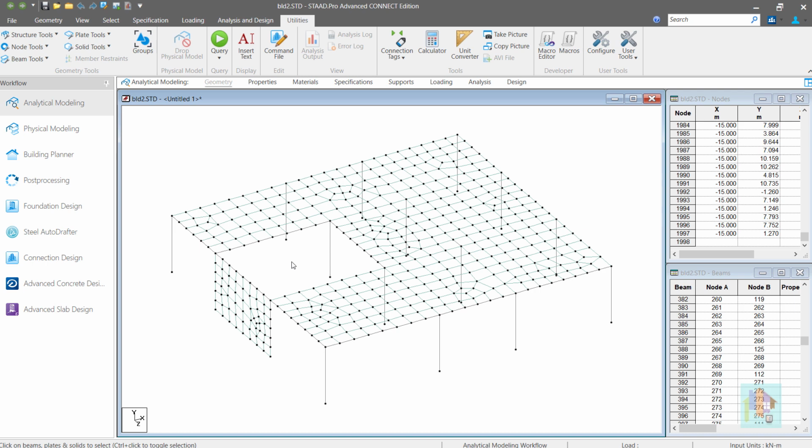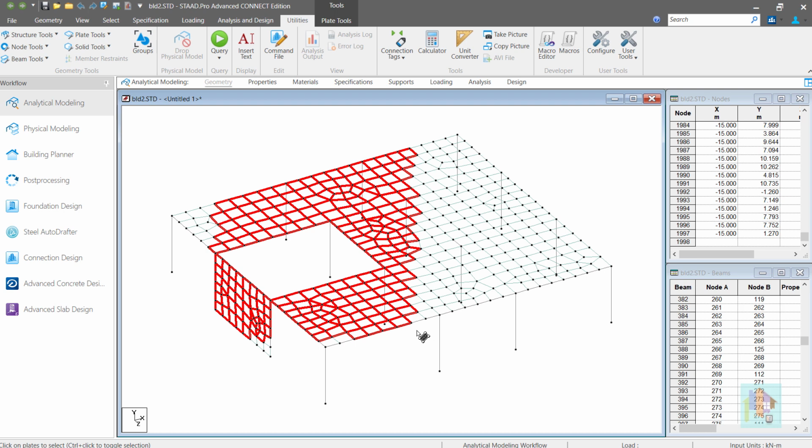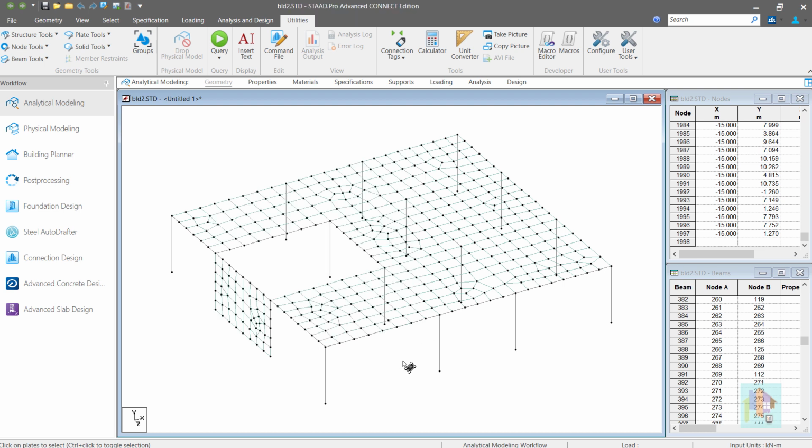And the most critical one is probably the plate modeling. First, we have to ensure that the plates are properly meshed and there is a connection established with the existing beam member. If there are some plates present, like an existing wall, then we have to double check the connectivity between the new plates and existing plates. And if you want to modify anything like changing the geometry, then we need to delete the entire mesh and remesh again, which causes some serious connectivity issues.